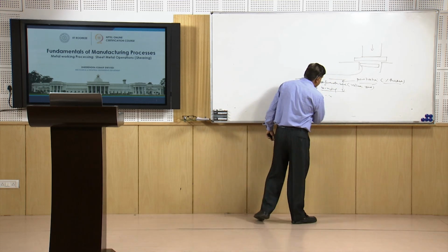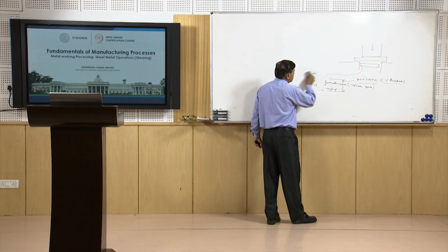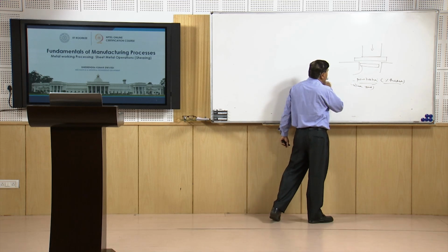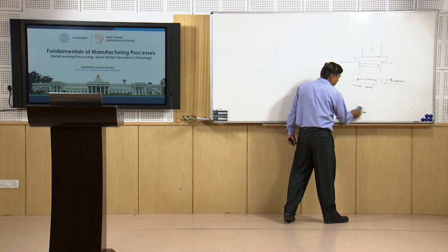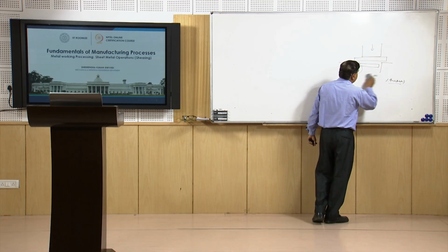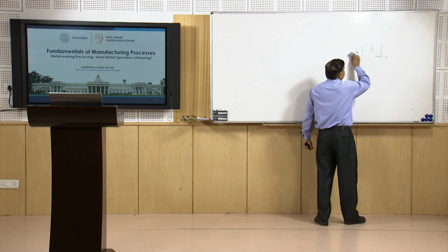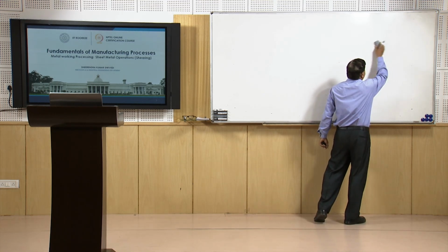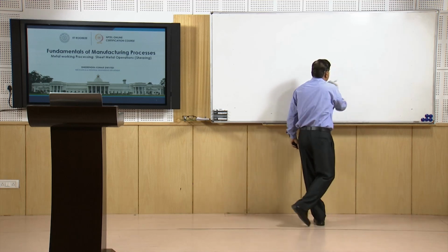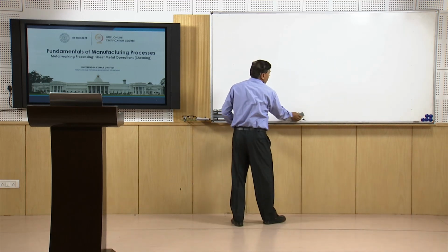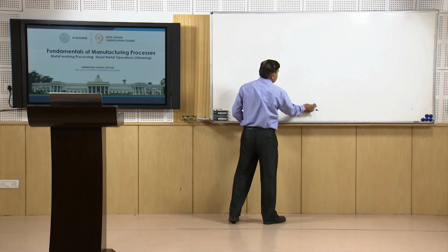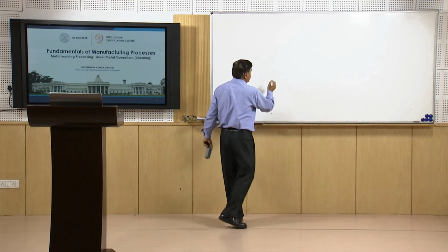When the punch moves down, the stresses on the sheet metal increase continuously, causing first the plastic deformation, and then leading to the penetration into the sheet metal.